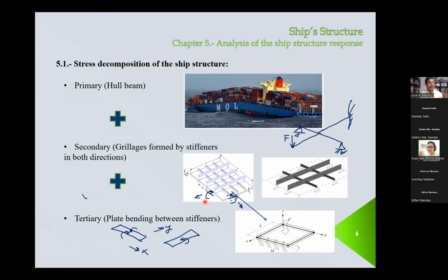When we are younger, including me, what we need to do is to analyze the stresses in many positions, and then confirm that even in the position where you have the largest normal stress, it's below the permissible stress. You can try to save some time, but it's always a good idea to do the checking. Check the stresses in several positions and confirm that in all of them, the structure is safe.